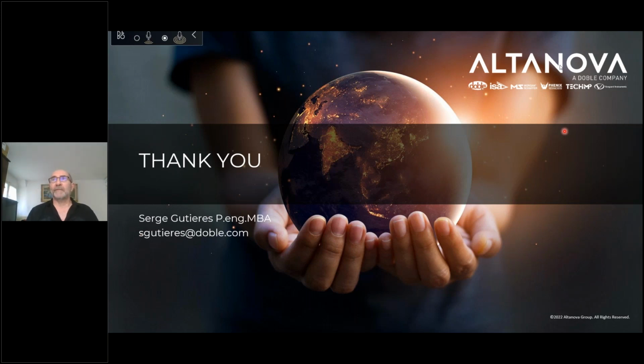Photoacoustic uses a combination of an infrared source, and the infrared goes to a filter that changes the light source frequency depending on the gas you're trying to measure. And then when that light source, at the changed frequency, hits the specific gas you're trying to measure in the measuring chamber, or the resonance chamber, let's say methane, that methane absorbs the energy of that beam.